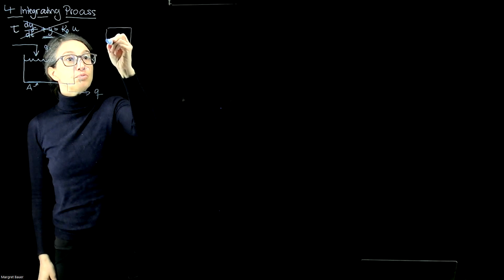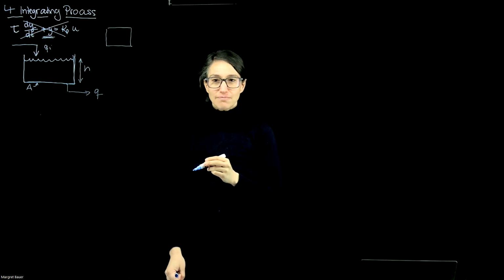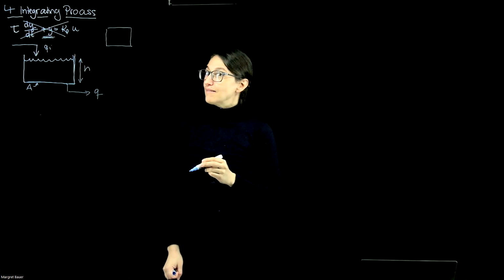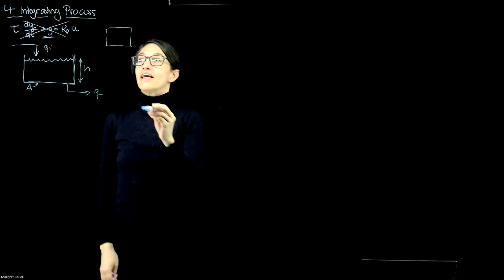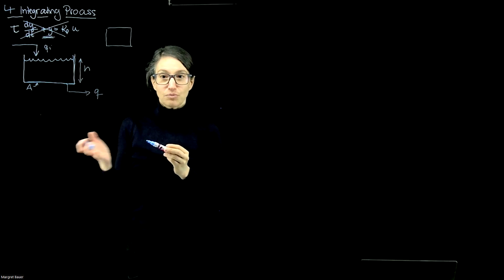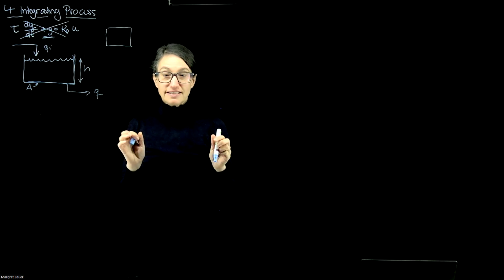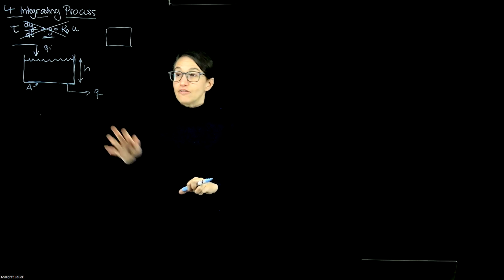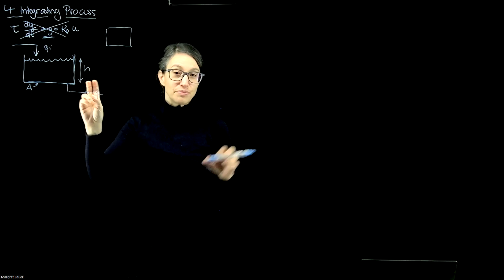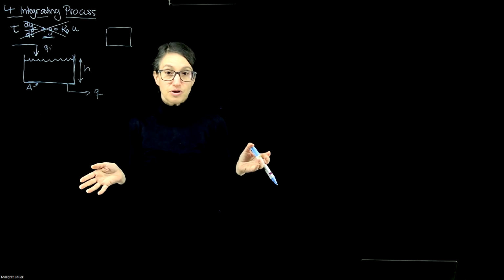Okay, and we can describe the dynamic behavior of this process as follows. First of all, we have to figure out what's our input variable. You can pause the video and think about it. What's the input and the output of the system? Okay, enough pausing. The input to our system is our flow rate. And we have to decide which one, the inflow or the outflow. For the purpose of this example, we're going to pretend that the outflow rate is constant. We're not changing that. It's for example 0, it could be a different value. The most important thing is that it is assumed to be constant.